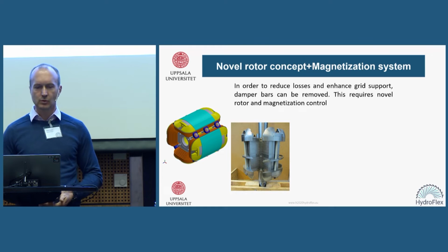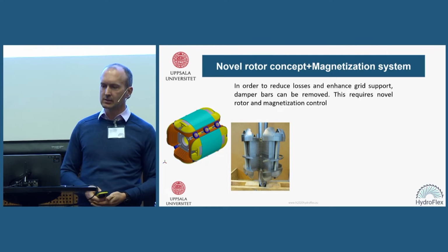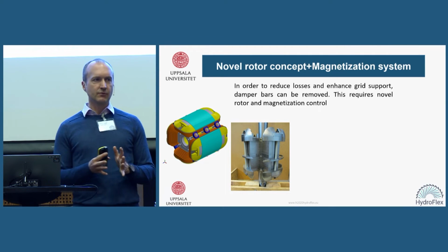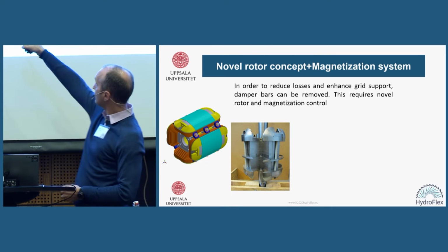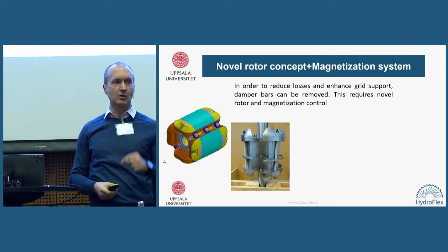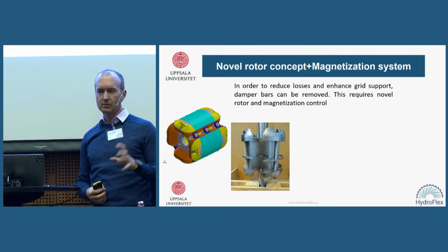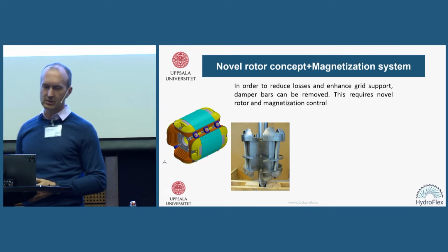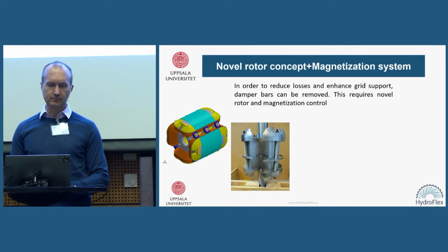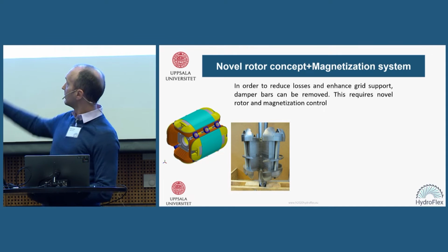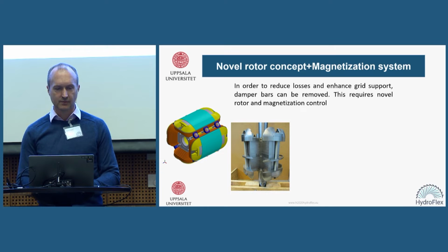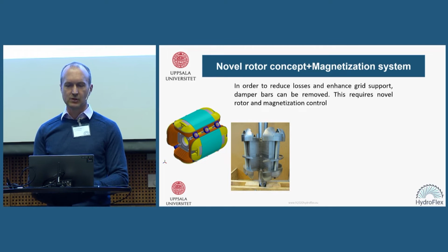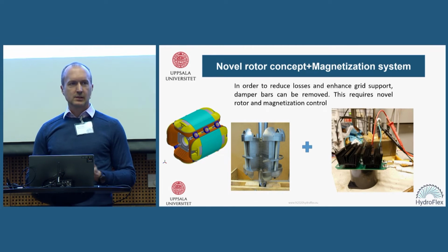So our rotor, which we have developed, looked like this. You can say it's a fully laminated rotor, but you see in the middle section here, there's a thicker bar. So it has some aspects also with damping, especially at startup and at different frequencies. The plan is that this experimental part would then look like what we have on the left there when it's fully manufactured. But this has to go together with power electronics.